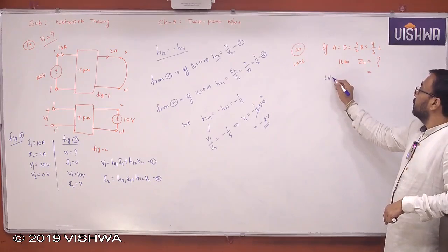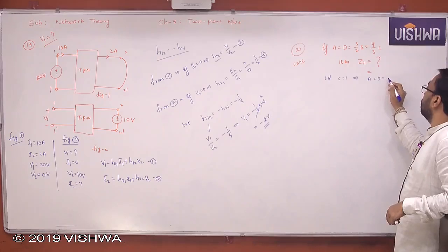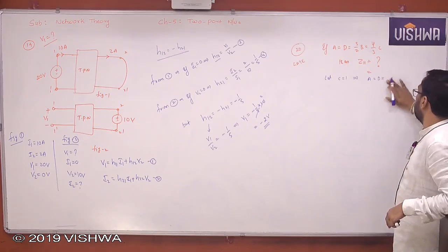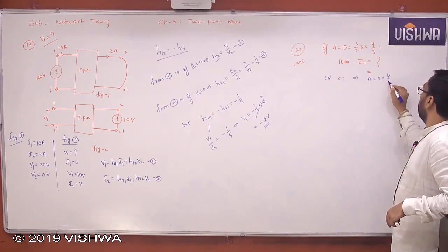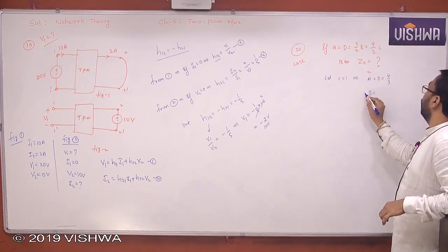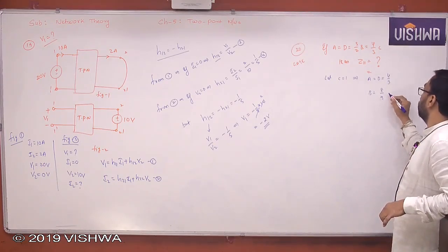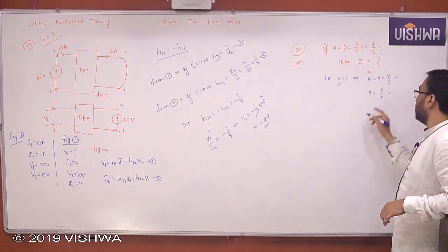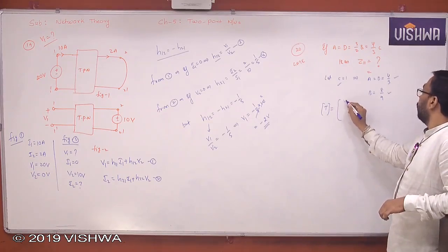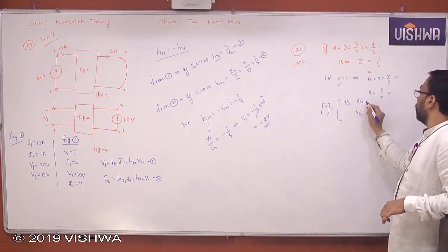Let C be equal to 1. From this, you understand A is equal to D, and 4 by 3 is equal to C, so C is equal to 1. Then A is equal to D is equal to 4 by 3. And B, then what do you get here? 3 by 2B is equal to 4 by 3C, so it will be 8 by 9. Already C is equal to 1. So A, B, C, D values are given. So what is the transmission matrix here? You got 4 by 3 and 4 by 3, 8 by 9 and 1. This is what you got.